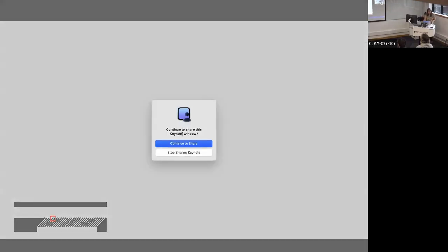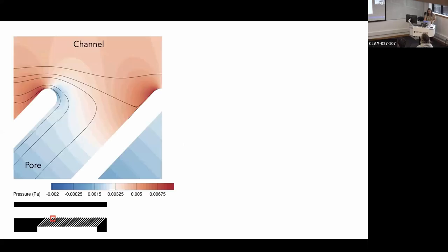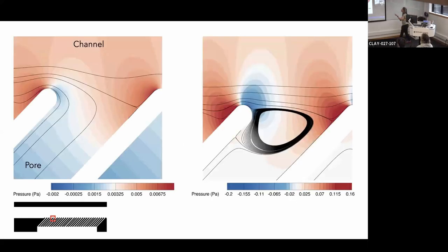So certainly there probably are regimes where you get more than one vortex. So the turbulent flow is up here where I have a high Reynolds number. And this gap is always still pretty small, right? So in this gap, you're sort of limited in what the flow can do. So as long as this is sort of millimetric or smaller and we're using water, you tend to get just one.